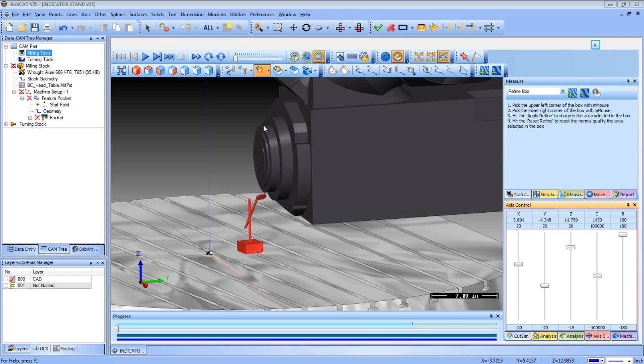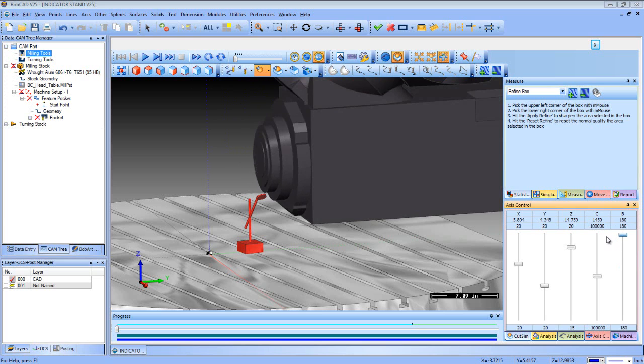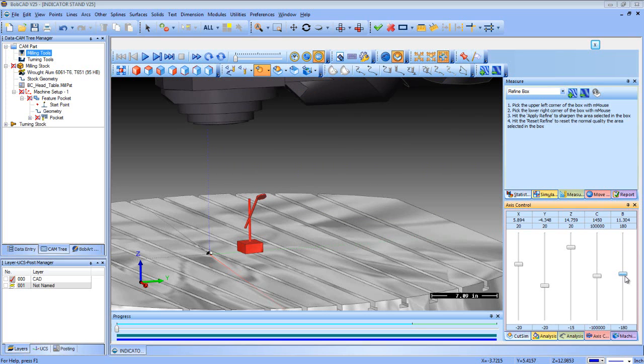Then you're going to measure the diameter of this point of the spindle and cut it in half to get the radius. Take that number and add it to the Z2. That gets us to the center of the spindle when it's cocked over at 90 like this. Then you're going to take Z2 and subtract Z1 from it, and that's going to give us our rotation point distance from where the head is sitting like this to this. We're going to jot that number down, and that's going to be our rotation point, and then we have the sine of our angle of 45.